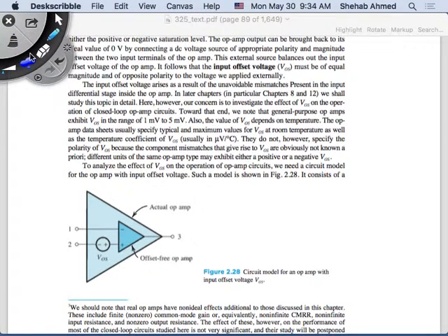Ideally, we would like, of course, to minimize the effect of these as much as possible, right? If we find a way to not amplify the offset voltage and have the offset voltage go through, fine. If it's a few millivolts and my supply rails are plus minus 13 volts, fine. 2-3 millivolts, and the output may not be too much harm, right? I may have to figure out a way, maybe I remove the average from the output, or I do something at the output. In all real op-amps, there will be offset voltages. They will have bias currents.